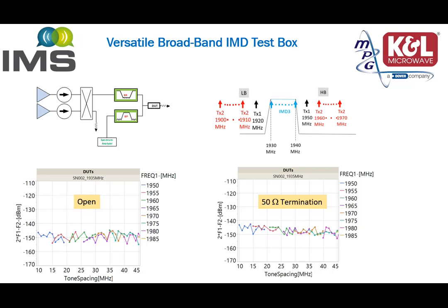Our goal is to create a versatile system where the transmit signals can be swept over a broad band range. The only condition is that the mixing product of the third harmonic or the fifth harmonic always lies in the band covered by the bandpass.